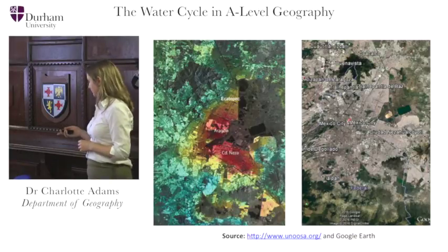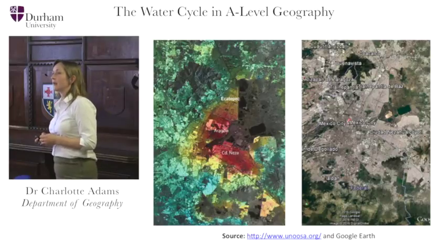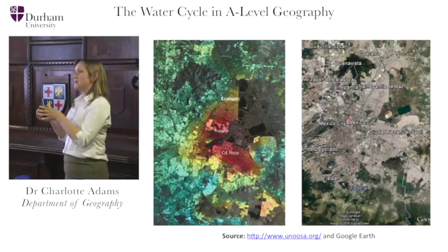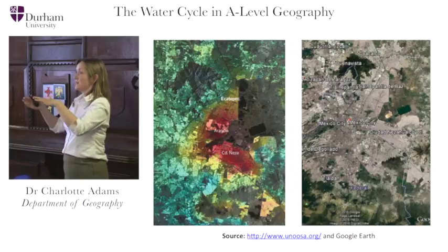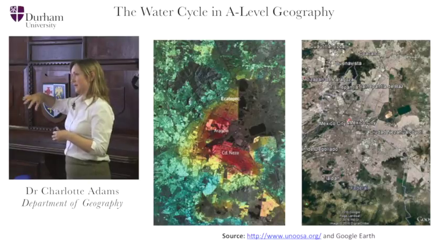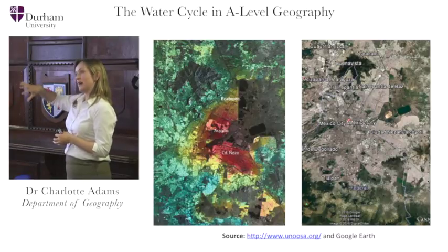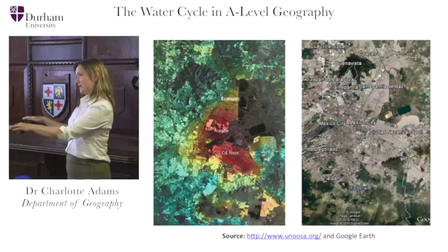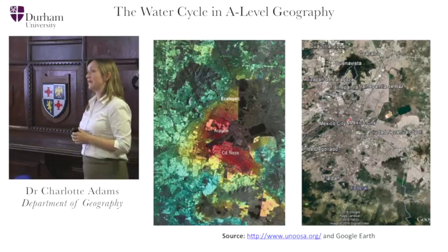Can I ask why the monument hadn't subsided? I think it was overlying bits of the aquifer where, basically, they're abstracting from a deep confined aquifer, and that wasn't beneath it, so there's like a tongue where that wasn't beneath it. So that bit was preserved and everything around it sunk down. So I think they were just lucky, really.